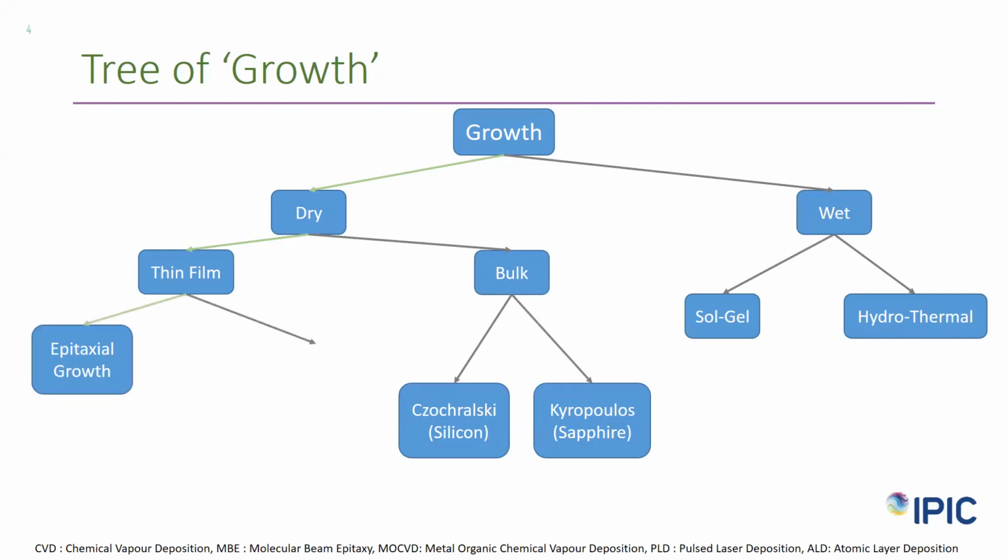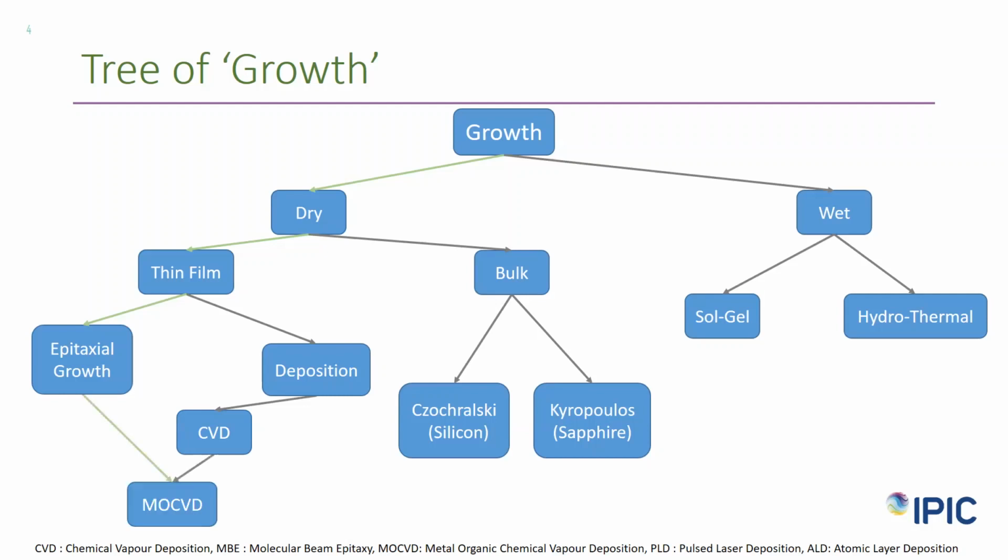Now, thin film can be reclassified into epitaxial growth and deposition. There is a very thin line of difference, and many times that line is very blurred when differentiating epitaxial growth and deposition. But still, deposition can be attained using chemical vapor deposition. Now, this was evolved and utilized with epitaxial technology to achieve MOCVD. I will say MOCVD just because this technology is available at Tyndall and is used to grow photonic devices, those epi layer devices which I had earlier shown you in the previous slide.